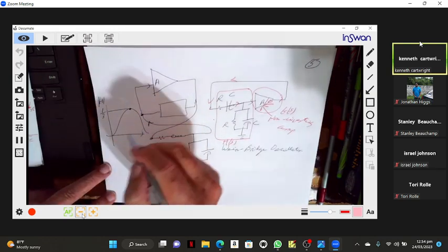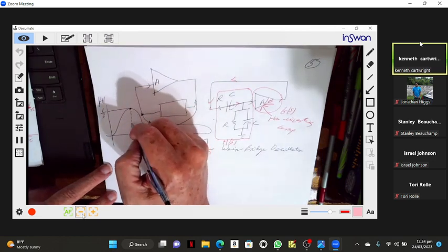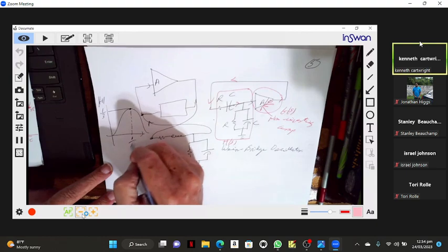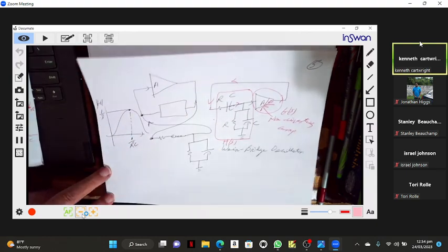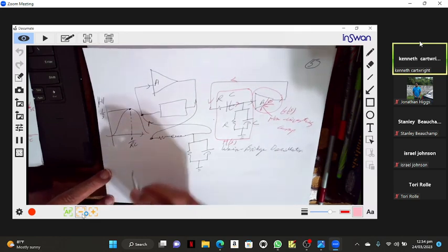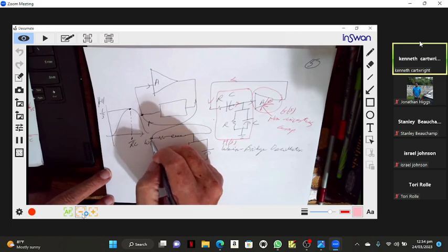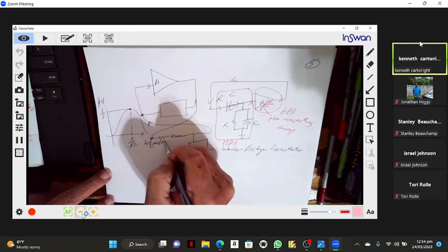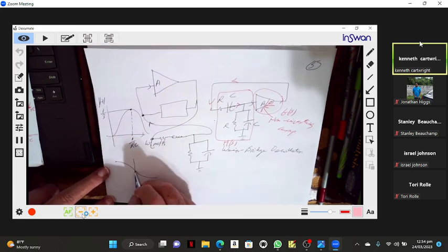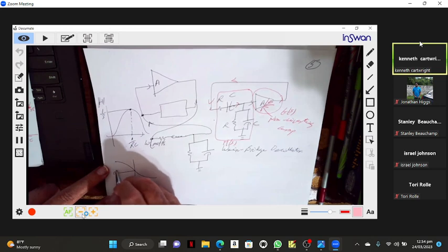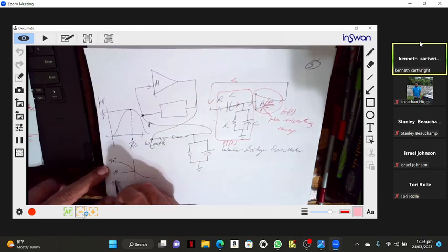If we have time later on in the semester, I will derive this for you. And this happens at 1 over RC. We have a magnitude and an angle at 1 over RC. This is omega. And the phase looks like this. This is 0 degrees, this is 90 degrees, and this is negative 90 degrees.